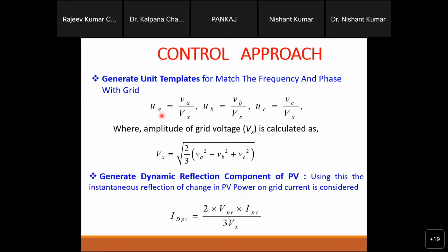And these signals will be used for synchronization, because whatever the grid frequency, we will not calculate the frequency, we will just generate the signal based on that frequency. If the frequency is 50.005 or 49.999, this signal will also be based on that, right? Because this signal is coming from the grid. So accordingly, these signals will follow that. So this is used here for grid synchronization purposes.